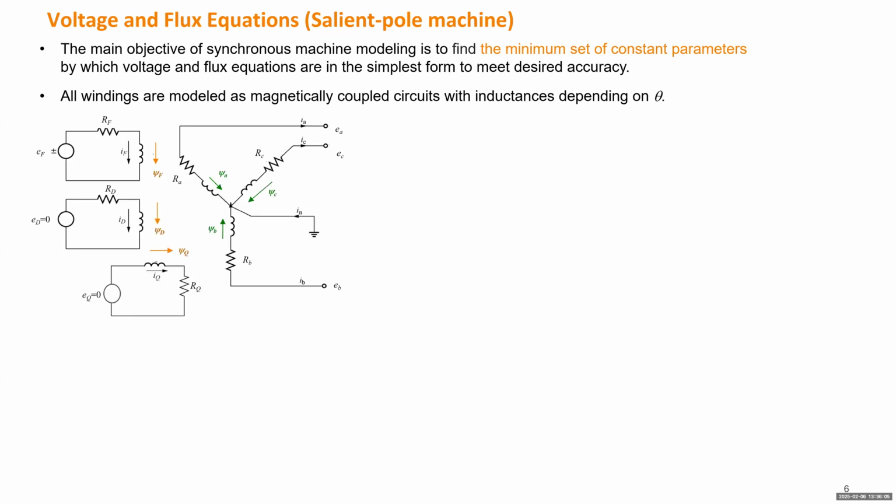Okay, so to model those windings, if we treat the stator windings and rotor winding as stationary, they don't move at all. We can borrow some ideas from transformers, right? For a two winding transformer, you just have one primary winding and one secondary winding, and the two windings are coupled. They're not electrically connected, but they are coupled through the electromagnetic field.